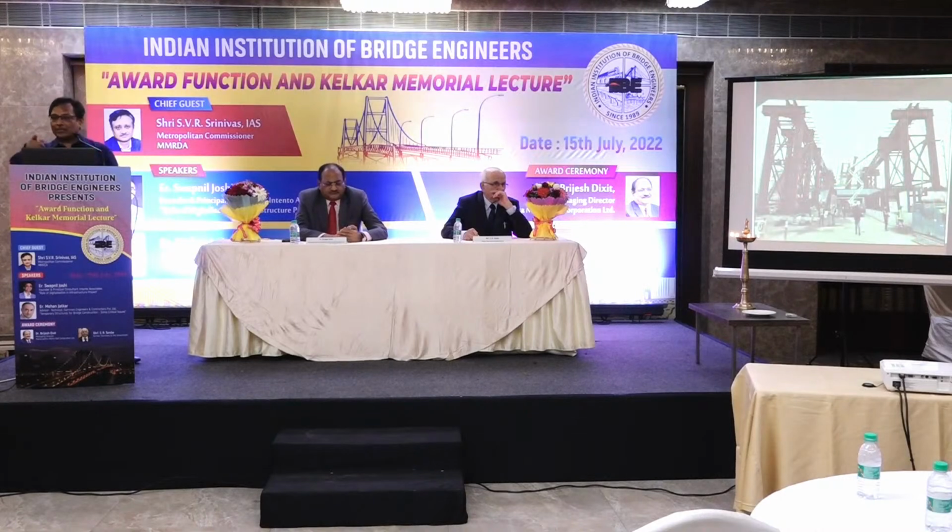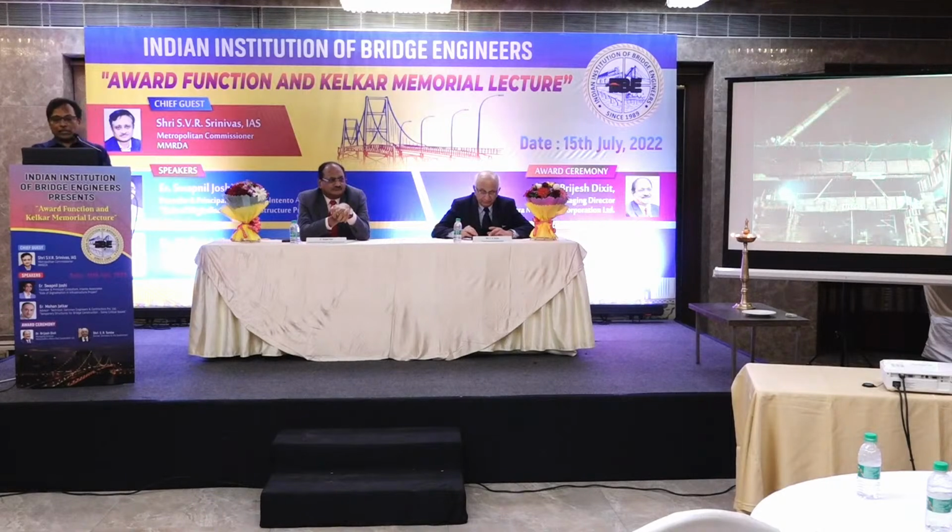I think one of the speakers talked about temporary work. You can see the temporary work. These are all temporary works, all supported over these vertical cylindrical steel pipes. A temporary girder was provided there, and on top of the temporary girder, our main girder was assembled. Just for the information, the weight of our temporary structure was almost 1000 ton. Our main structure was 1600, and the temporary structure work was carried out. Of course, after the work was over, this is all scrap. You can see that these are again temporary works across the railway track.